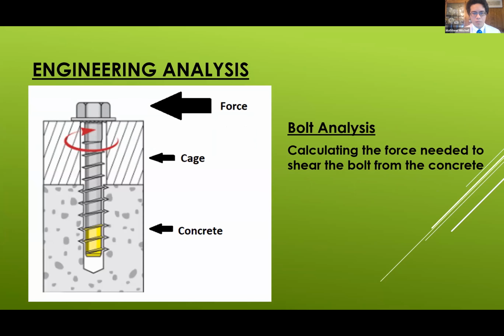So next up is our bolt analysis, and that's to mount the cage to a concrete floor. We will be using grade 8 half-inch bolts, which will be 2.75 inches long. After doing some calculations, I found that the first mode of failure will occur in the cage itself at the mounting hole due to bearing stress.